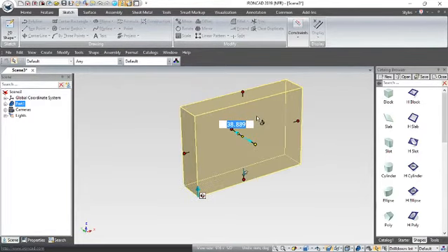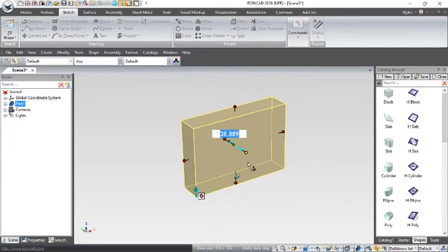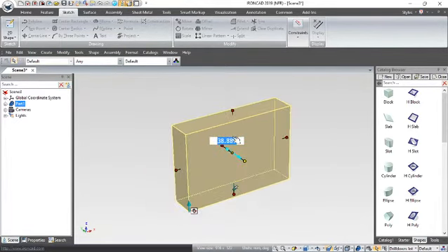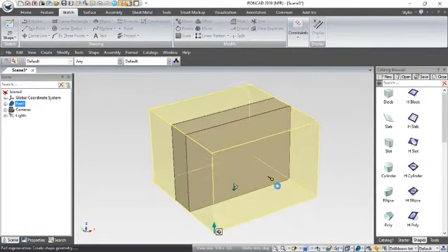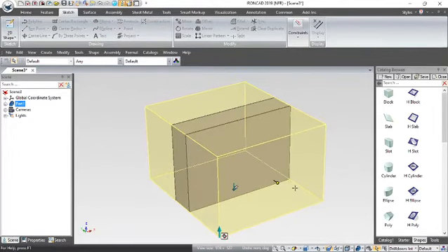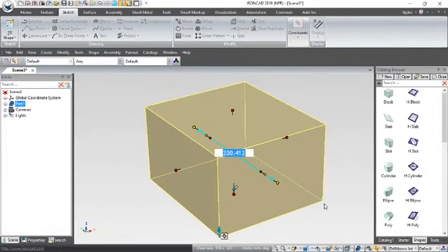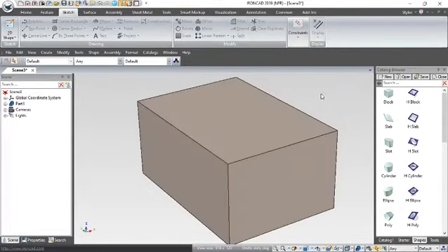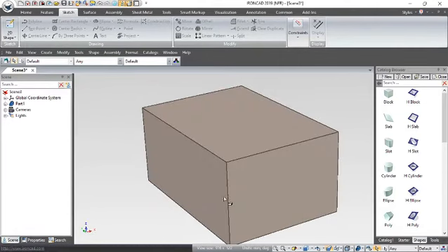And finally I'm going to pick on this icon here, which is basically the width. If you're doing the width, you might want that to be symmetrical about that anchor point. In order to do that, you'll see there's a little yellow icon there, and if I pick on that yellow icon, you'll see the other handle's gone yellow as well. Now if I move that with my left mouse button, it's going to be symmetrical about the center of the shape. So I'm going to make that 250 millimeters.